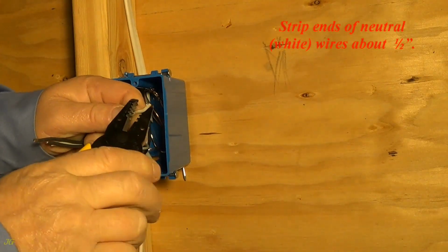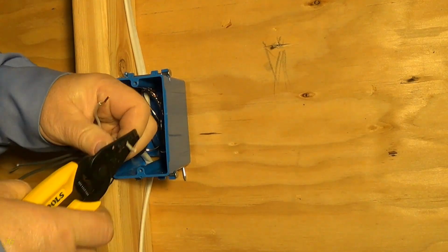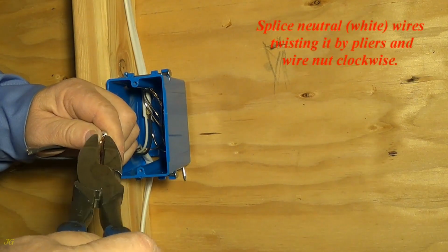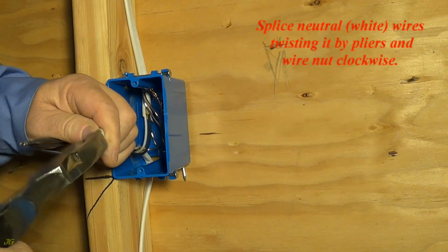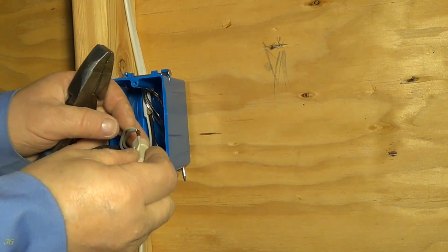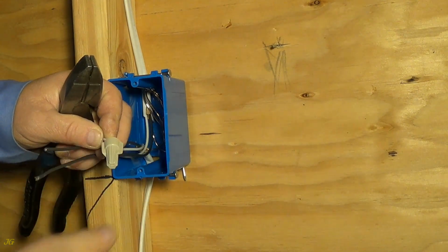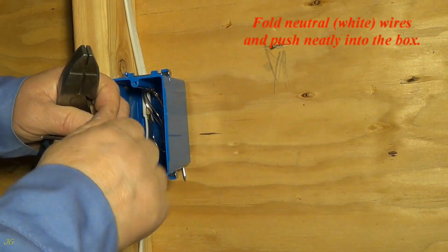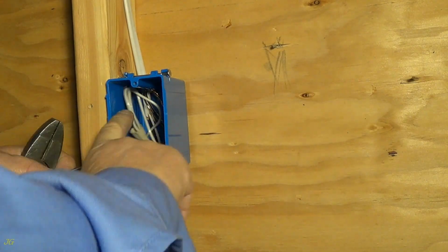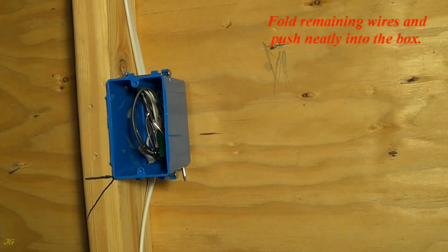Strip ends of neutral, white wires about 1/2 inch. Splice neutral, white wires, twisting it by pliers and wire nut clockwise. Fold neutral, white wires and push neatly into the box. Fold remaining wires and push neatly into the box.